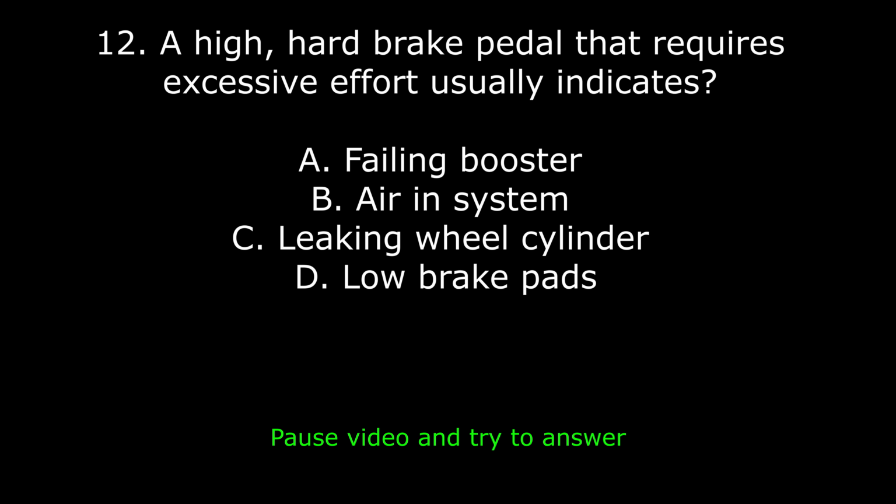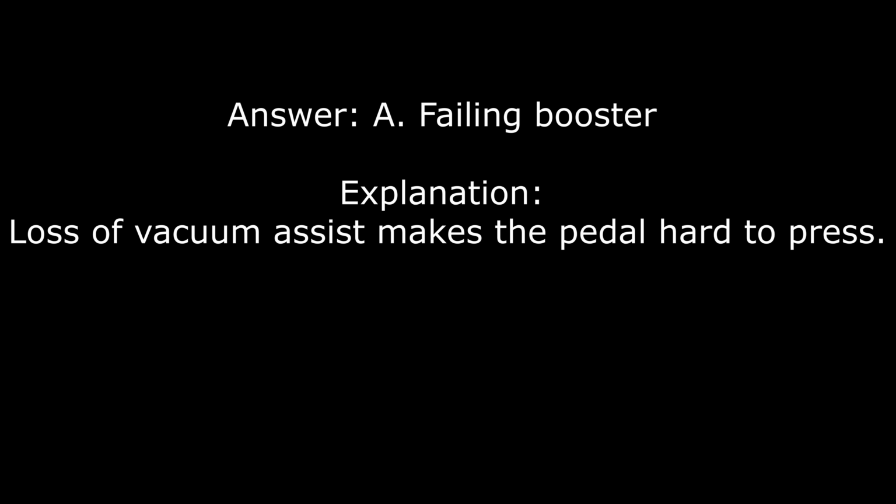12. A high, hard brake pedal that requires excessive effort usually indicates A. Failing booster. B. Air in system. C. Leaking wheel cylinder. D. Low brake pads. Answer: A. Failing booster. Explanation: loss of vacuum assist makes the pedal hard to press.